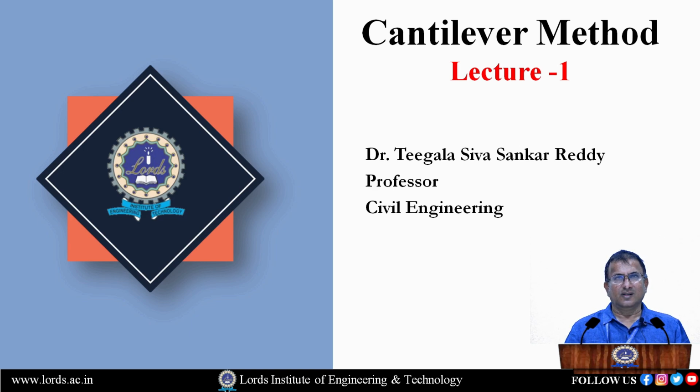Today, we have the discussion on analysis of multi-story frame by approximate method, that is cantilever method. To analyze the multi-story frame, we have three approximate methods. The first one is the substitute frame method, the second one is the portal method, and the third is the cantilever method. We will apply the substitute frame method when the frame is subjected to vertical loads, whereas the remaining two approximate methods, that is portal method and cantilever method, are meant for analyzing the frame when it is subjected to